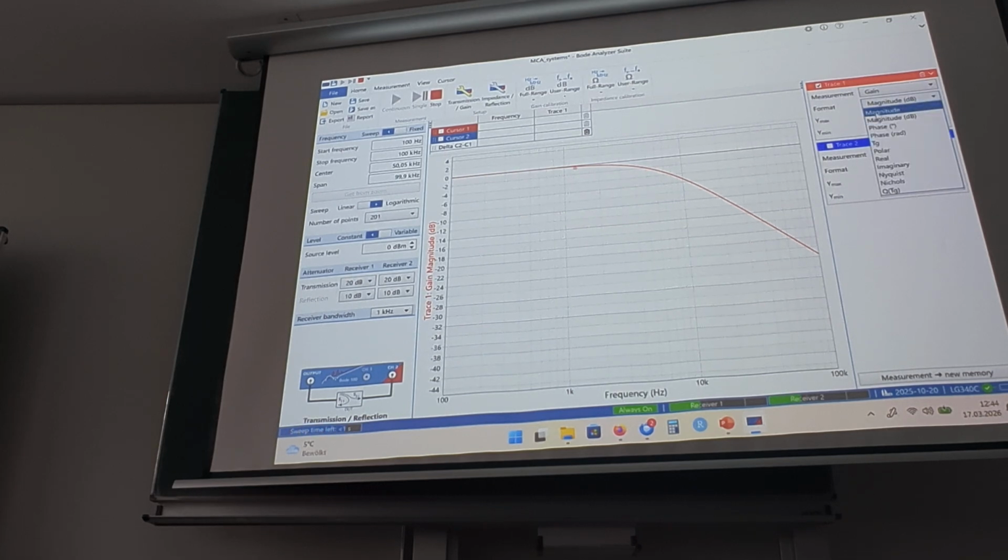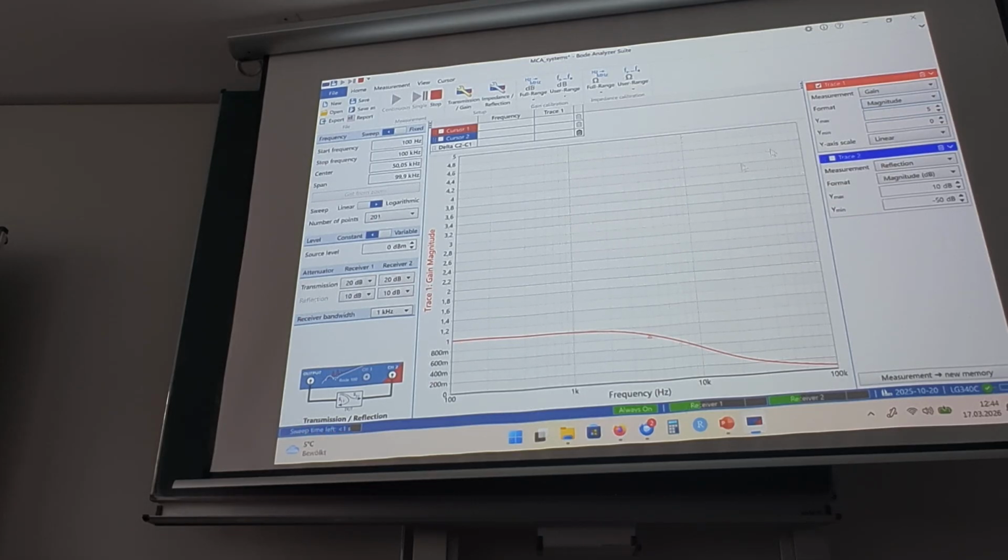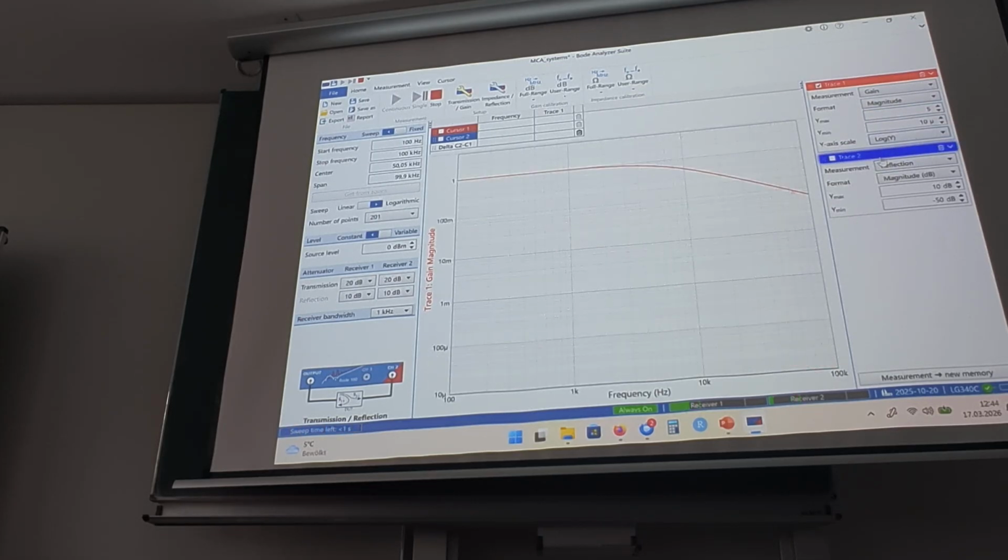We can just show the magnitude in values, logarithmically and optimized. Okay, so the ratio is 1. That means we always have exactly the same amplitudes at the input and the output. But for higher frequencies, the output voltage becomes smaller and smaller. So this is the left part of the diagram that we saw, and this is typical for a first order system.